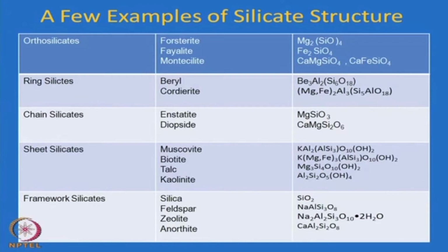For a high temperature material, in most applications one would like the thermal expansion coefficient to be low, so that there is not much volume change or change of geometry during heating or cooling, because if there is a sufficient amount of volume change, then there is a possibility of breakage and crack formation, and the material will lose its integrity.